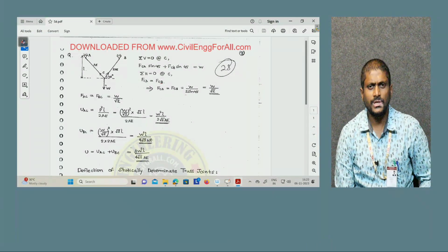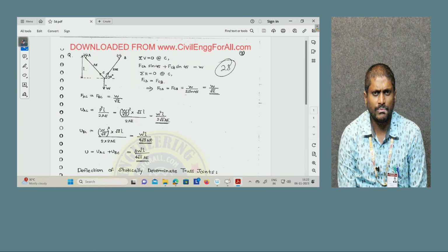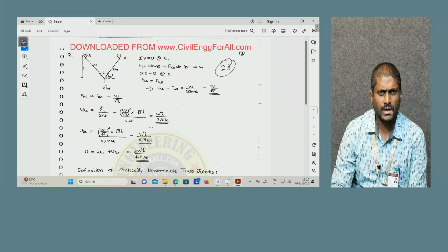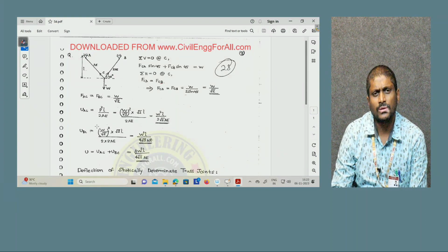Then you will get FCA equals to FCB actually. Then from there FCA equals to FCB equals to delta by 2 sin 45 equals to W root 2. So this is all about calculation of that forces. FCA equals to FBC equals to W root 2.